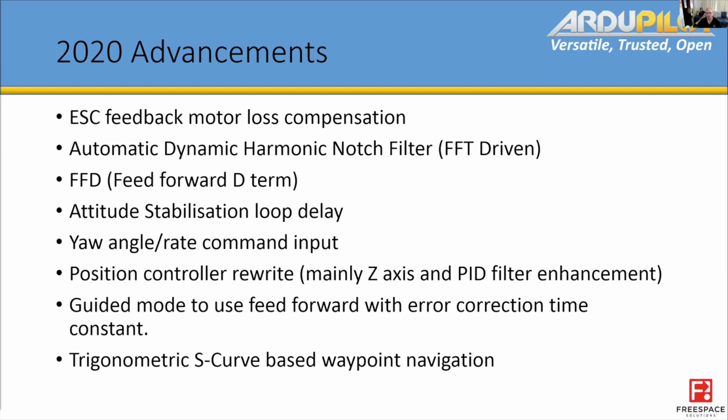Now, the yaw rate angle command. That's something I didn't quite touch on before, but basically it becomes really important for coordinated turns, because if you just have a target angle, the actual angle always delays it, because when you're producing a target angle, the actual rate of change is proportional to the angular error.